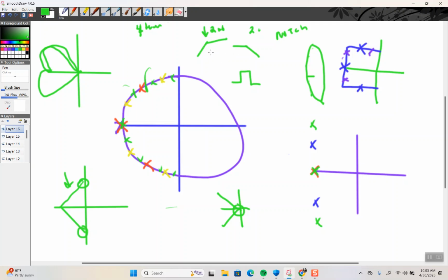For Butterworth, that damping coefficient would be 0.707. It won't just give you a fourth order notch, because a fourth order notch is really a second order high and a second order low. The band can be fourth order, but a fourth order filter there will be 40 and minus 40, because you're going up and coming down, where a fourth order low pass will be minus 80, right?